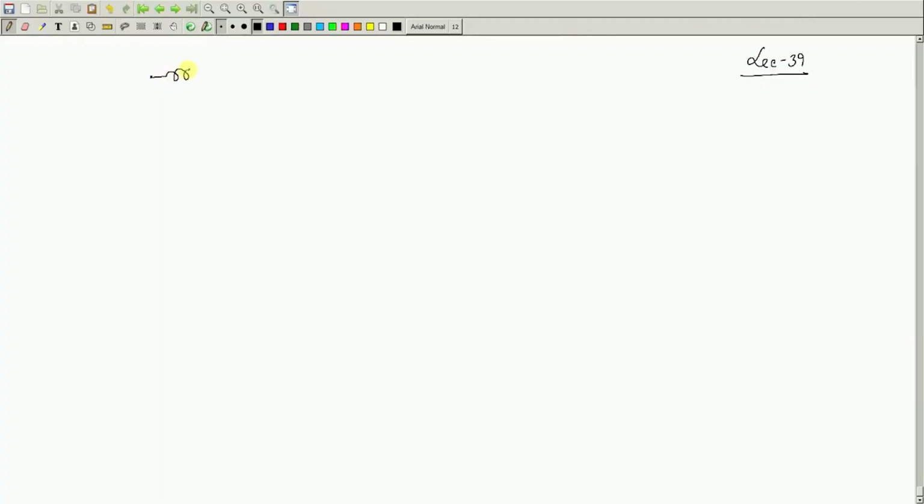Okay. And I told you that henceforth I will draw the coils horizontally, it does not matter. In my mind I know that these two coils are wound on some magnetic circuit like that, and if you show this is dot, this is dot, it is sufficient so far as finding out or writing down the KVL where mutually coupled coils will be present. This much information I must expect, so that I will be able to write down the equations correctly.